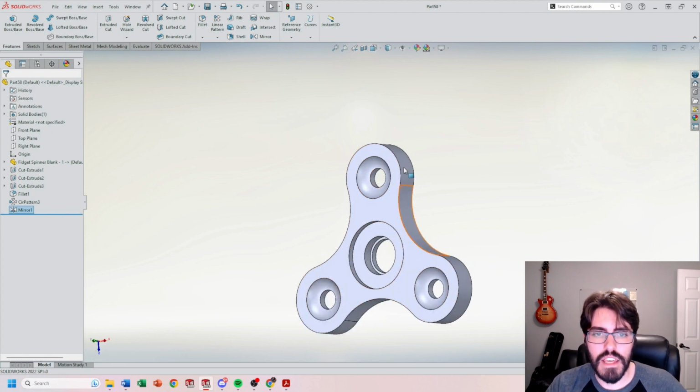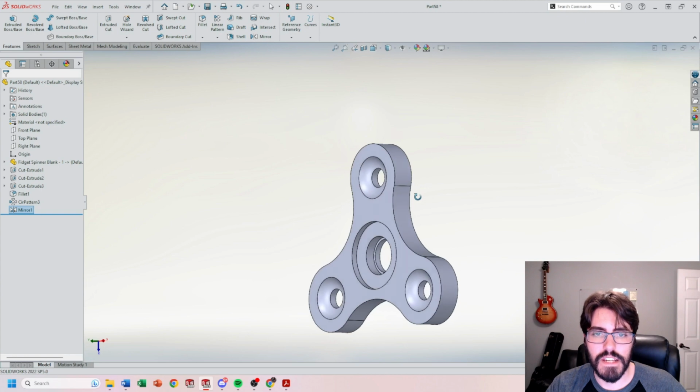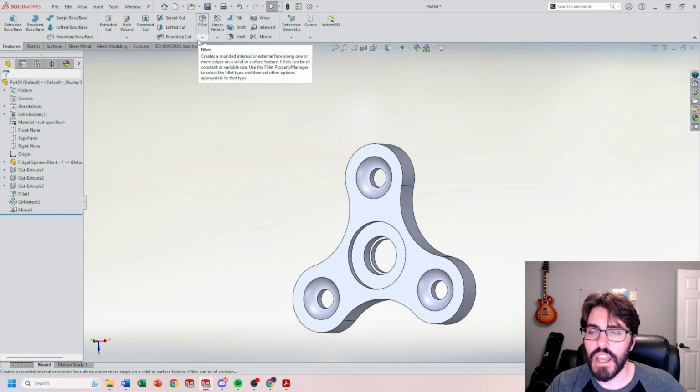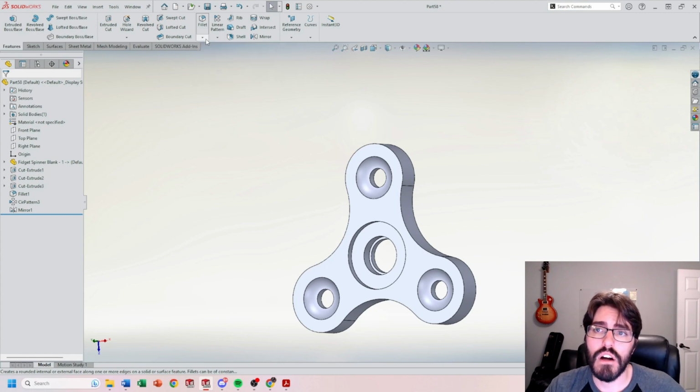Let's go ahead and apply the edge break of the outside diameter or the outside profile edge. So I'm going to go over here to fillet, and underneath fillet, I'm going to change this because I want to utilize this for a 5-axis swarf application. And instead of it just being a typical 45-degree angle, which we have a 45-degree chamfer, I want to change this to, let's say, like 30 degrees or 60 degrees or whatever degree amount that you want, because I can actually rotate and swivel the table in such a way that I'll simultaneously trace out the profile at whatever degree angle that you want. So I'm going to now change this to a chamfer.